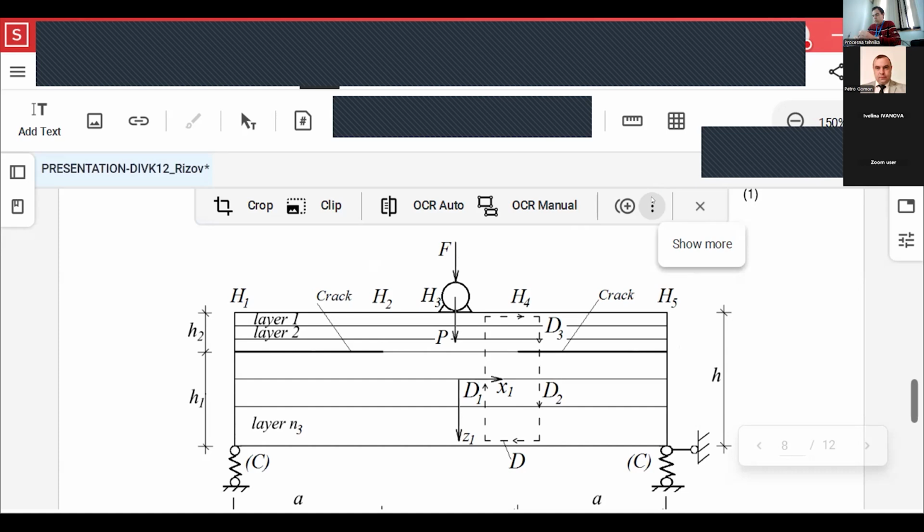The strain energy release rate is deduced from the energy balance in the conditions of harmonic load for checkup of the J integral. The extremals of the total strain energy release rate confirm the maximum and minimum of the total J integral. The evolution of the total J with spring constant, static, and harmonic load is qualified.